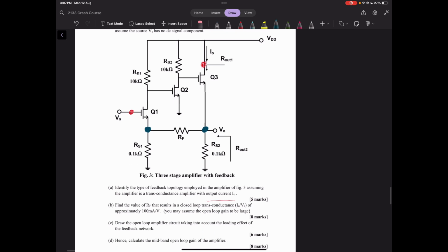So on the question of whether to include this resistor in the feedback network, it's pretty clear that we should, because we're taking an output current. Again, there's no current through here, because there's no current into the gate of a MOSFET ever. You can see here that's labeled as an open circuit, even in the MOSFET diagram. So if we change this resistor, this would very clearly change the I out current, which would change how much of that current is being fed back. So it's pretty clear that we need to include RS2 in our feedback network.